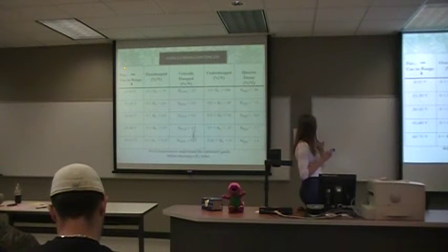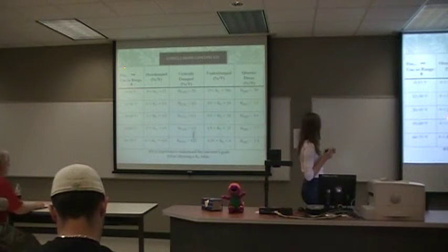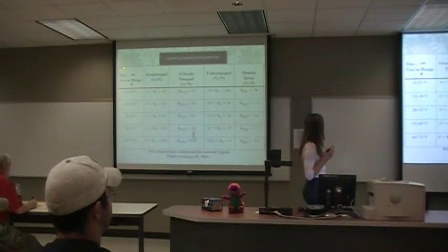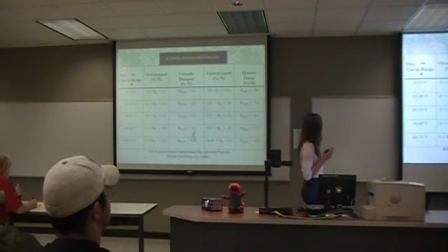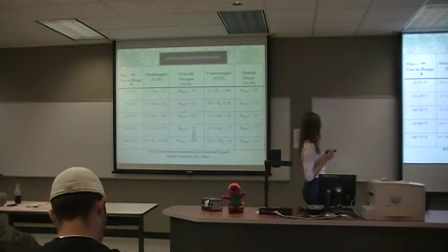We put together this chart so you could just see what values of Kc you would choose for different damping situations. But it's important to understand the customer's goals before choosing the Kc value. So for use in a range of 0 to 15 volts, if you want overdamped, you're going to use a Kc from 0 to 15. Critically damped Kc needs to equal 15. Underdamped, 15 to 186, and then a quarter decay is 38.